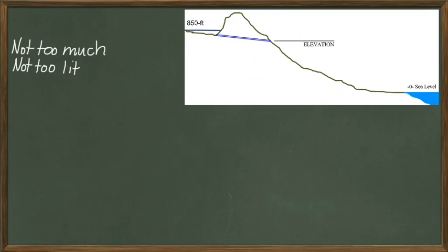Within a given water system, we try to manage the energy in our system. We neither want too little nor too much pressure. Too little, and the water is of little use to the end user. Too much, and it can damage our distribution systems and even the plumbing of our homes. For this reason, a water agency must establish a static head criteria in order to limit the pressures within their system.